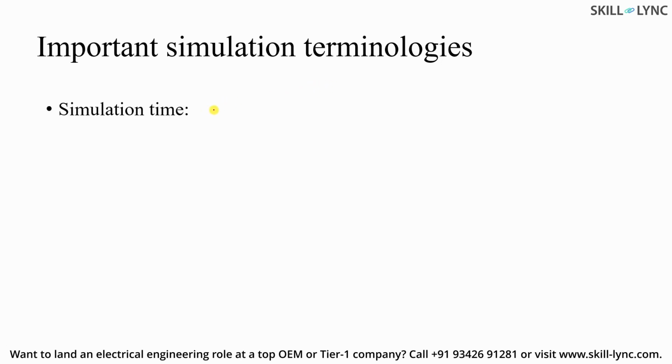The very first thing is simulation time, which is nothing but the stop time in our case. The stop time is what we have seen in the Simulink window, and it is for how much duration you want to run your simulation. That is called the simulation time, and this is the first important parameter for configuration.